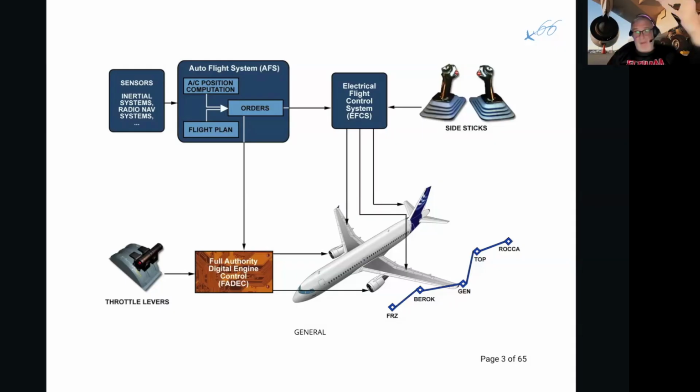Throughout the duration of the flight, from the climb detent, the auto thrust is engaged until the pilot physically takes the throttles and moves them out of that climb detent. Even when the engines spool up or spool down, the throttles are completely independent of the thrust, which is managed through the FMGCs in a different way than on the Boeing.